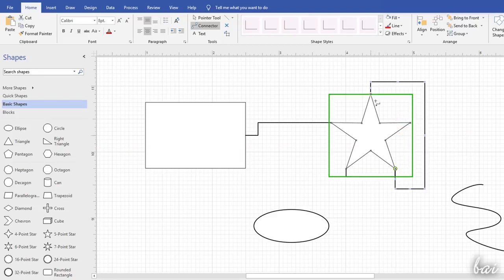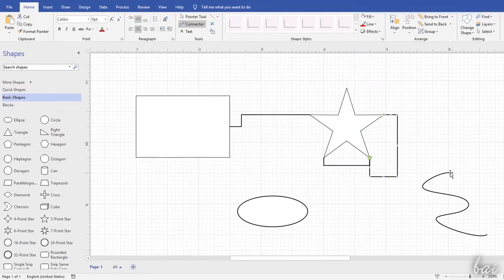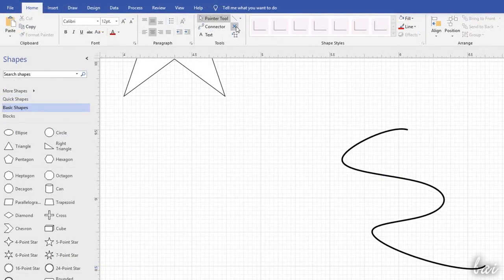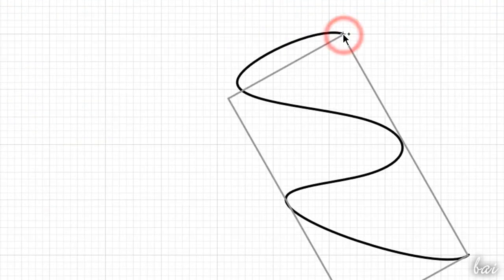All shapes created with ready templates do include connection points and contours, but all the custom ones made with the drawing tools do not, so it becomes hard to create connections with these unless you create connection points first. To add connection points, select the interested object and enable the Connection Point tool from the Home tab. At this point, hold down the Control key and click on specific points on the shape or outside it to add a connection point represented in pink color.